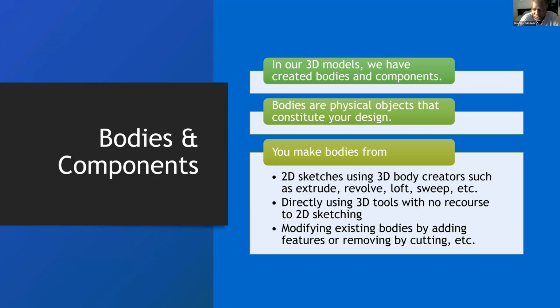And what you will do to make that happen is to work on the relationship between the body and the other bodies that appear in your design. When you have a situation where one body can enter another body, that is not a model of reality, and that shows that there's something wrong with your design. Because you know, one critical rule in reality is that 2 solids cannot occupy the same space at the same time.